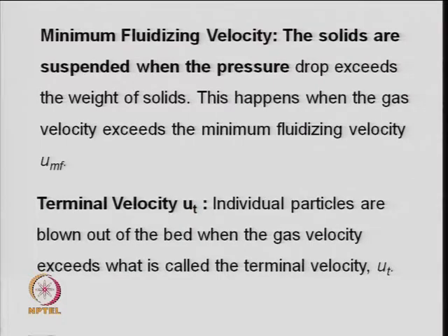Suppose there is a wide variation in the particle size, then it may not be good, because fine particles will be leaving the bed and larger size or coarse particles will not be able to fluidize under the given velocity condition. So, one needs to design or identify the conditions required to fluidize.